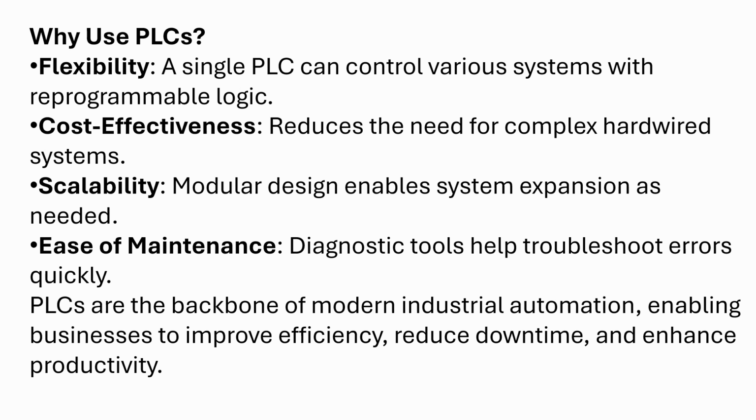Also, PLCs are cost effective. It reduces the need for complex hardwired systems. Scalability, they're modular. So a lot of PLCs you can expand, you can add modules, add more inputs, add more outputs as needed. You can have remote I/O. You can have a central processor, a local rack, and you may have remote I/O in another part of the building that's all tied into that same controller. So it's very, very flexible and the scalability is very important.